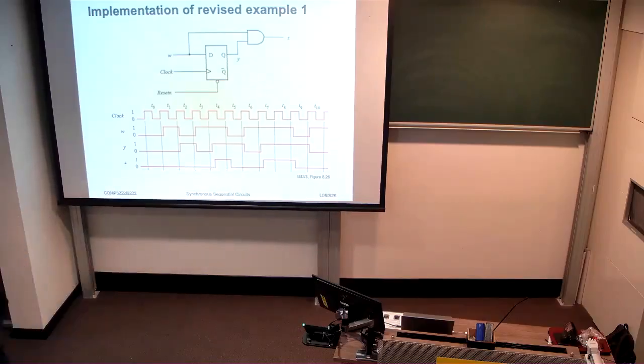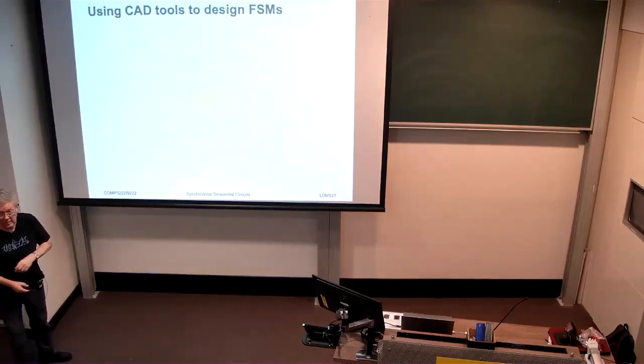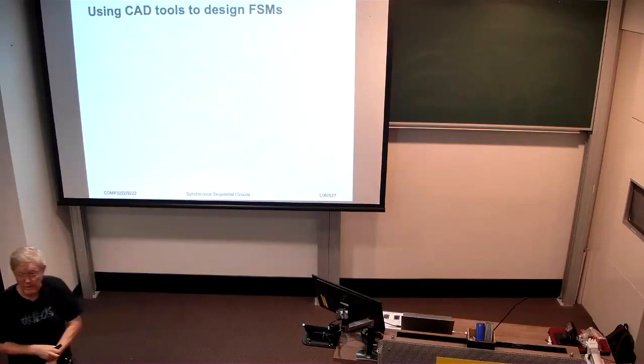All right, so we've seen that it's more responsive, but there's also sort of a bit of asynchronous behavior here. This output is now dependent upon the input. Every time the input changes, even if there's no change in state, we could potentially see a change in the output. So that's something that has to be borne in mind. All right, and I think that's probably a good point for us to have a 5-minute break.